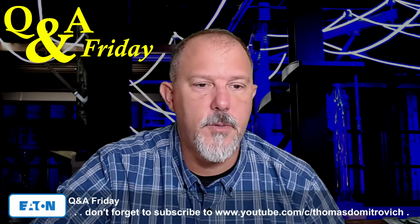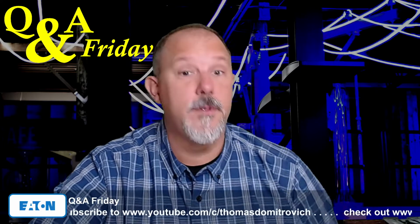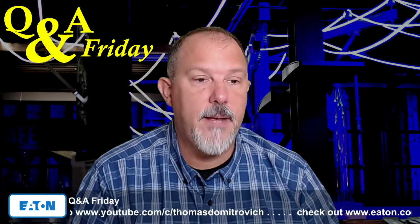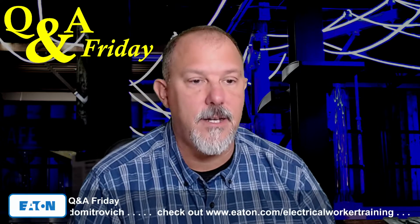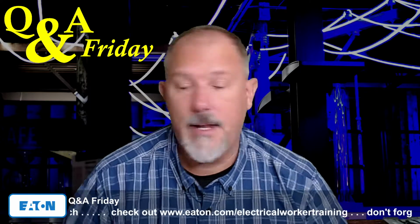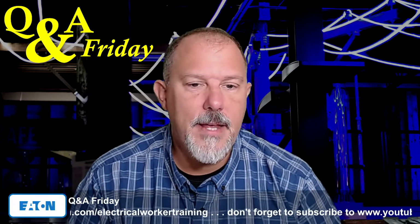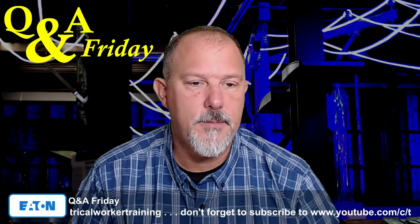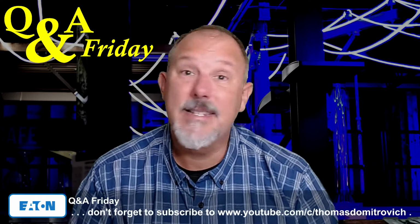I think the question the person asked classically is whether turning the 2000 amp breaker down to 1600 amps would make it meet the exception in 210.20 for a 100% rated breaker. Oh, I remember this one, this was a good one. The answer is that it doesn't. That's true, it does not. And that's what I tried to explain. If I didn't come across that well, I apologize. The answer is that it doesn't automatically meet the exception if you seal it at 1600 amps. That is correct. It doesn't meet that.